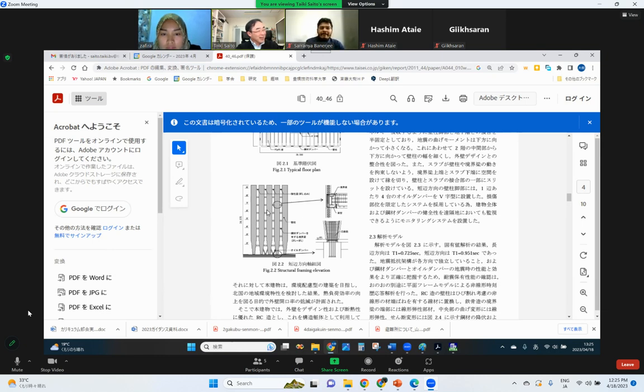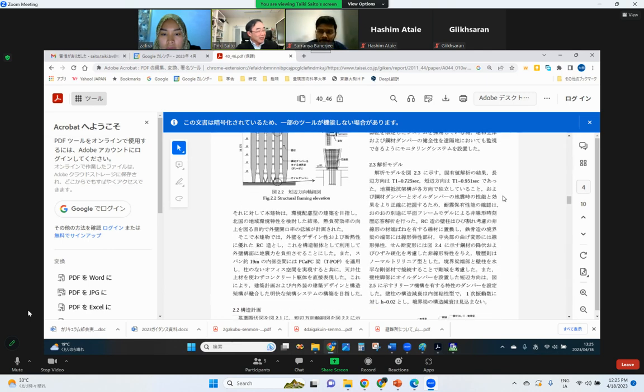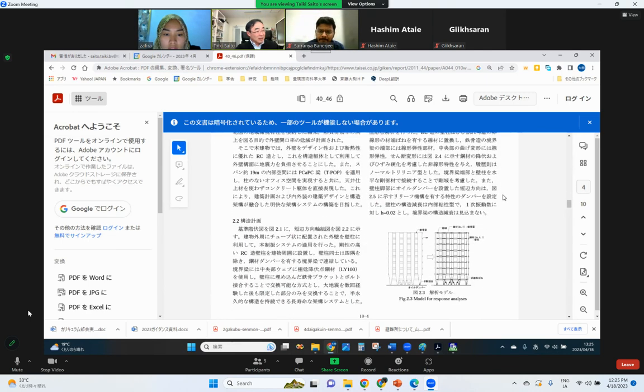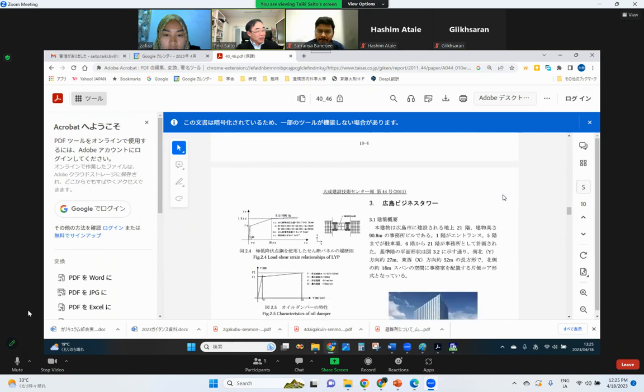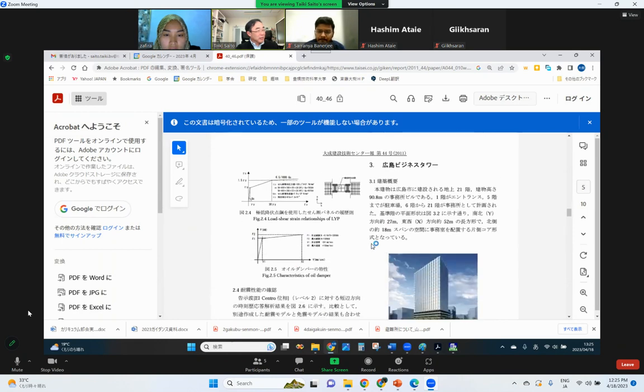There are one, two, three, four, five shear walls, and the bottom part is almost pin supported, very slender, right? So it's easy to turn over, but they're connected by dampers. Actually, this building is already constructed. Anyway, the damper is a hysteresis damper. Yeah, hysteresis damper, maybe.